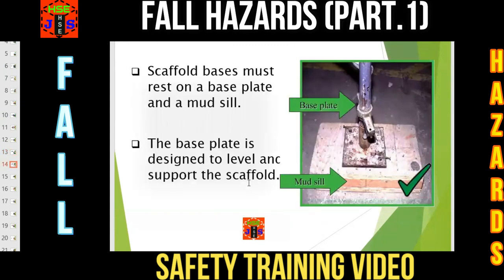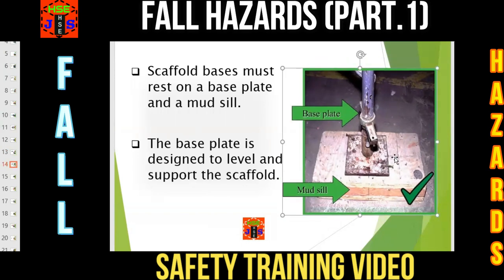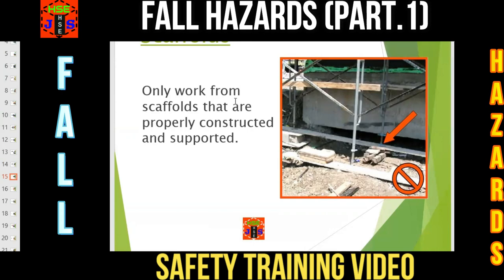Have a look. Scaffold base must rest on a base plate and a mud sill. The base plate is designed to level and support the scaffold. This is an example of a mud sill, and this is a base plate. This erection, this work practice, is absolutely safe. Dear friends and fellows, you have to work only from scaffolds that are properly constructed and supported.